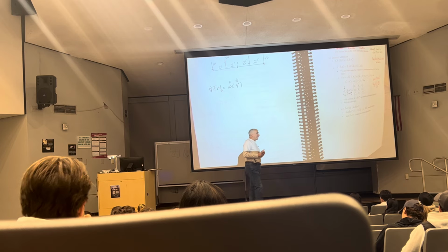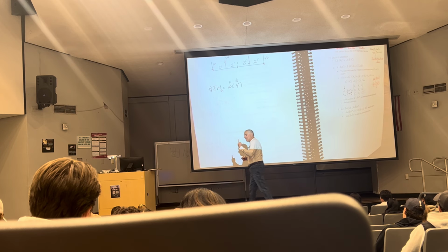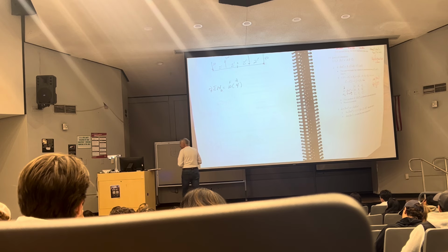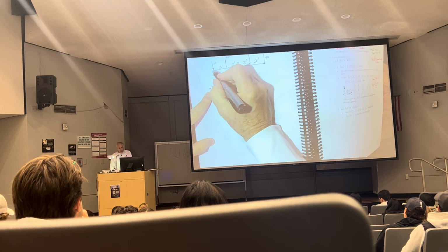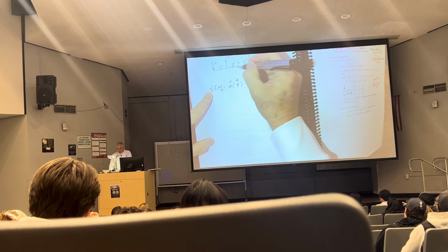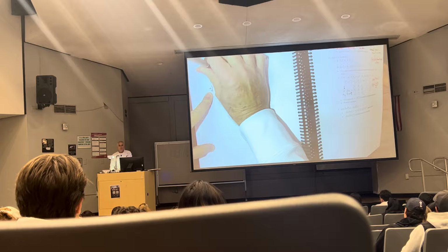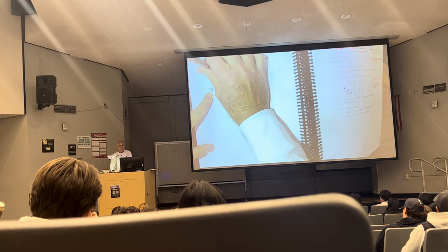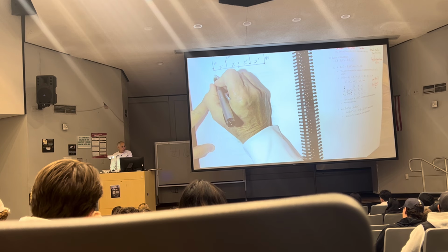Now you have to come up with the sign. It's either positive or negative, depending on what you see. So I chose clockwise positive. Is this generating a clockwise moment at O? Well, how do I know? Take your pen. There it is right there. You with me? Follow it around O in a natural way.